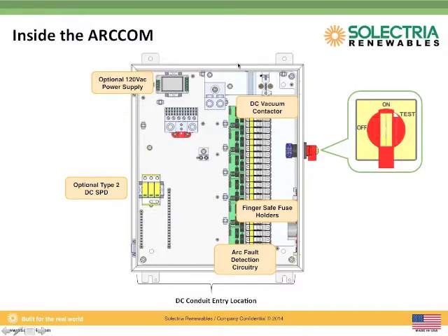Now, this box is designed to take power in two different ways. Natively, it accepts 24 volts DC. It has an operating range of, I believe, 19 volts DC up to 26 volts DC, and it has an optional 120 volt power supply. Now this is actually 120 volt native, but it's actually capable of going up to 277 volts line to neutral. And what this allows you to do is run an AC feed with greater voltage drops. So you're able to run 120 volts and drop to 100 volts before this actually drops out, because the threshold on this power supply is actually 100 volts AC.